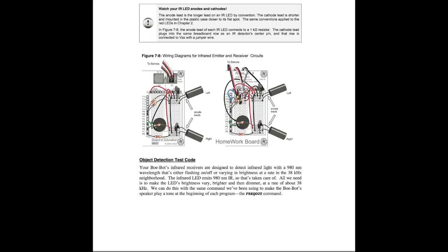And remember, this is a 3-pin transistor. So when light comes in, we'll get the power coming from VDD flowing through, because the base is set up by the infrared light coming in, and that will send power to our I/O port. So we'll see a 1 if there's light coming in to our infrared receivers. And it's the same thing on the other board pretty much here. Same exact wiring, it's just that there's the extra servo stuff that's kind of in the way.